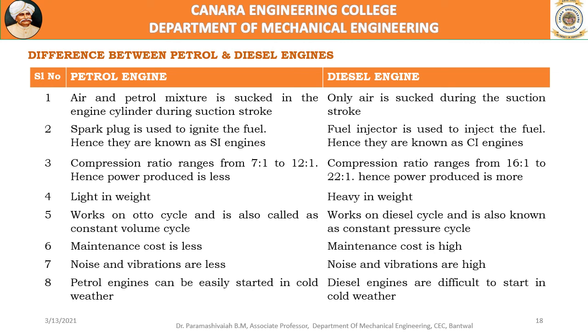The gap volume between the cylinder topmost position and the TDC is called clearance volume, and the total volume is the volume of the cylinder when the piston is at BDC. That ratio of clearance volume to the total volume is called compression ratio.